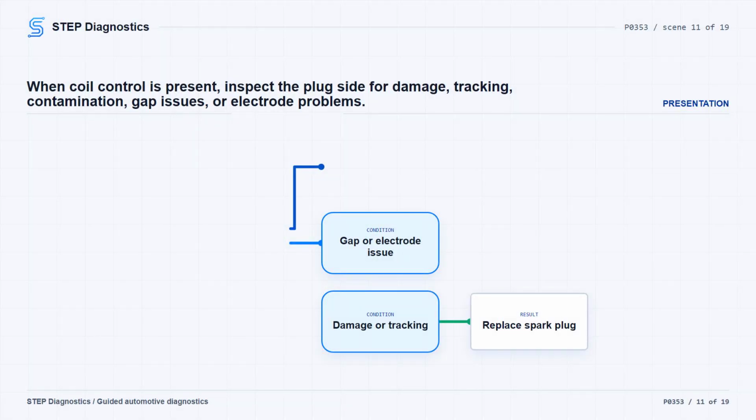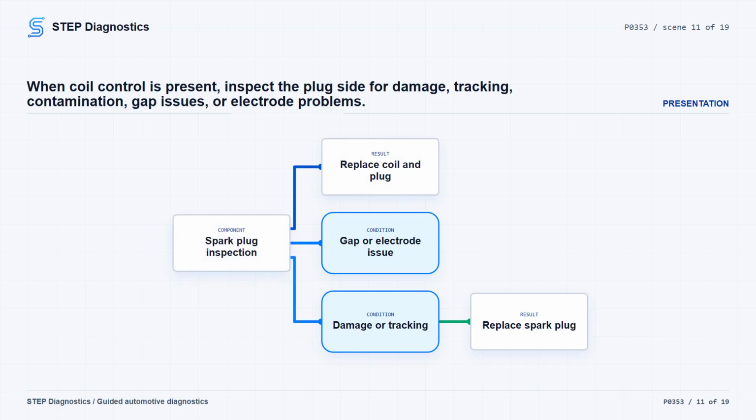When the control light is blinking brightly, turn the ignition off and remove the spark plug or plugs as required. Inspect for cracks, carbon tracking, foreign material, gap size out of specification, and a loose or broken electrode. If one of those conditions is present, replace the spark plug. If carbon tracking is found on the plug, inspect the ignition coil boot for damage and replace it if necessary.